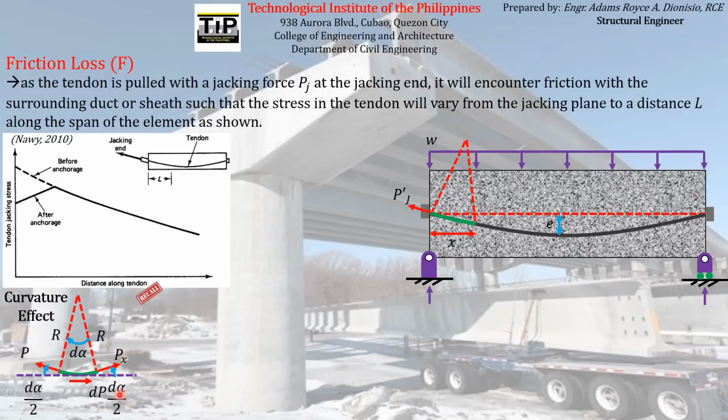And if you can recall from statics of rigid bodies, friction force is equal to mu times the force perpendicular to the friction force, which in this case is this force. Let us call this normal force, normal to the friction force, the differential normal force. Again, differential because we are talking about differential lengths or differential values here. Let us call that dN. So mu here is the coefficient of friction, if you can remember from statics.